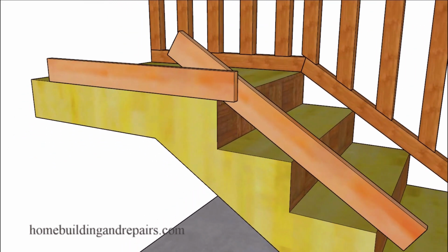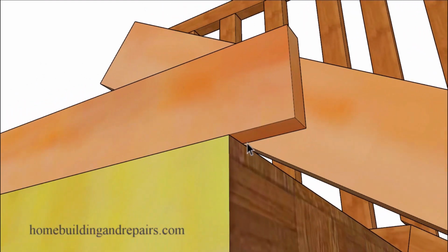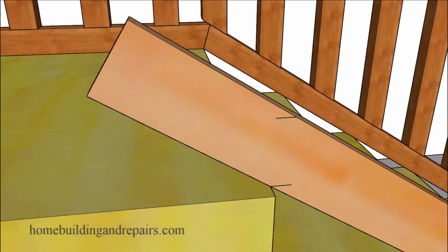So basically what you're going to do is take two boards, and these boards should be the same size, maybe a 1x4, and lay one of the 1x4s on top of the stairway like this, and the other on top of the floor or the landing. And then just simply mark the bottom. We're going to mark this right here. We're looking for the intersecting points here and here. So mark the bottom and the top with a pencil, and that should look something like this.